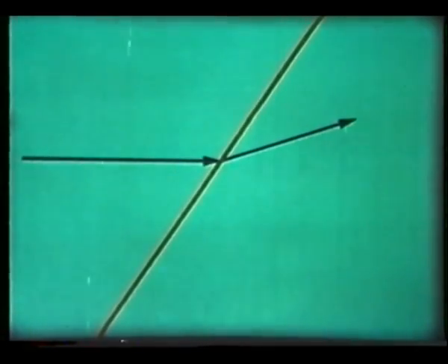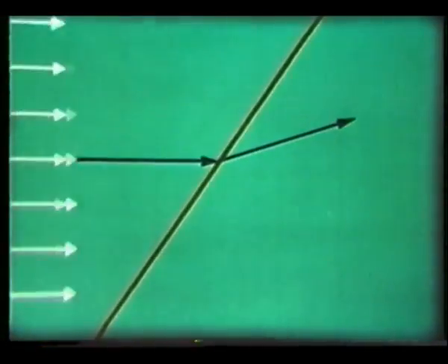If now the whole picture is turned round, nothing is changed. The shock wave is oblique to the airflow and has deflected it and slowed it down. Pressure always increases when velocity is lower. And if streamlines are drawn, they are closer together past the shock wave than ahead of it.